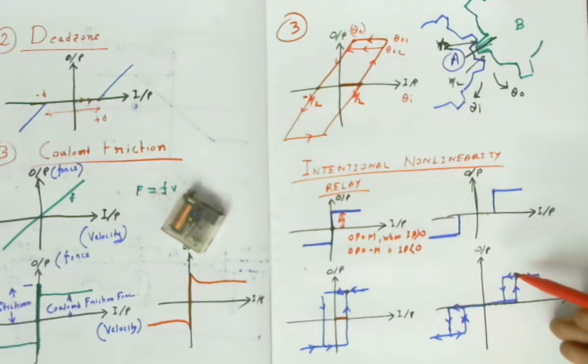It will not necessarily happen that from 5 volt to 4.9 or 4.8 the relay coil de-energizes. So up to say 4.7 volt, it is all still energized. So the output is still on. A 5 volt relay means it requires 5, not exactly 5 volt, it may require 4.5 volts. But it will never operate at 3.5 volts.